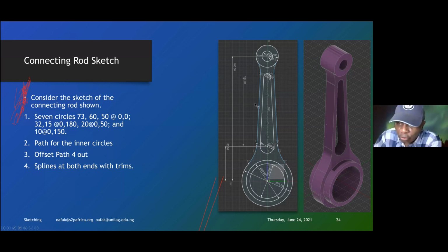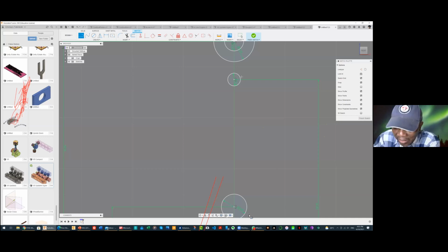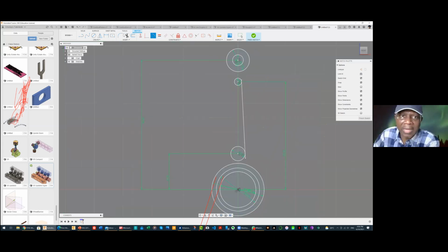So what you are going to do, let us make this thing look big. And then you take a line. Once you want something to be tangential, you just take something near it. You don't let it be tangential exactly. Okay, so after you have done that, you now take the tangential constraint. So this, and then this. So that's tangent constraint.